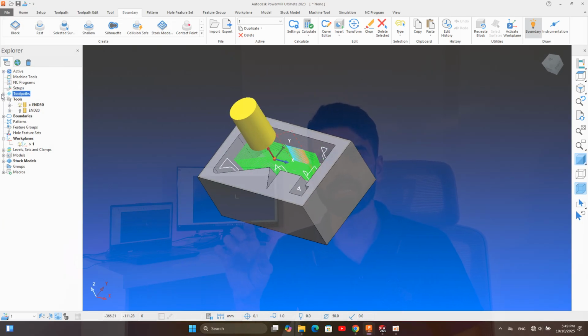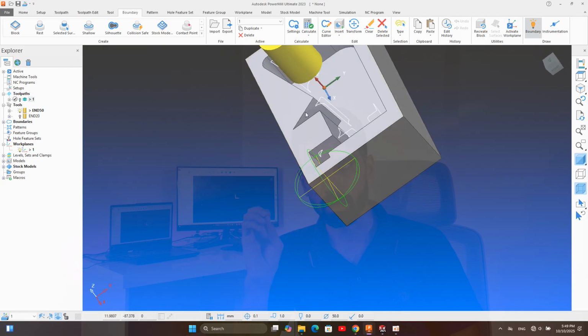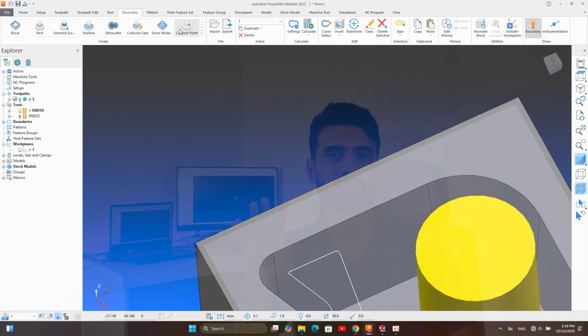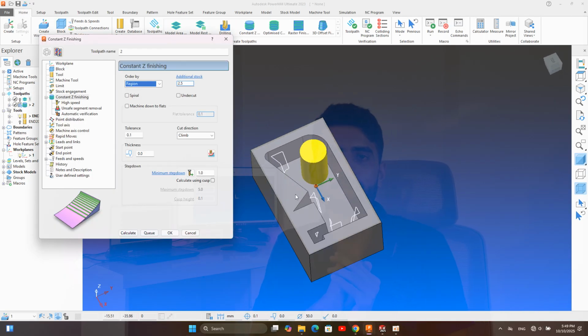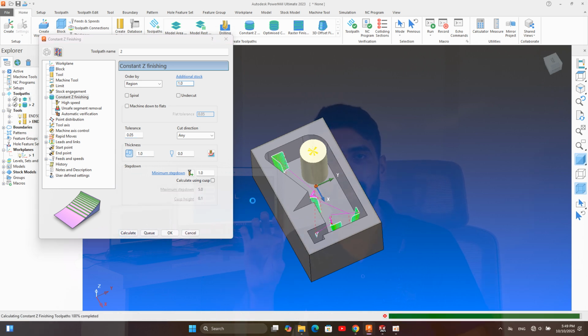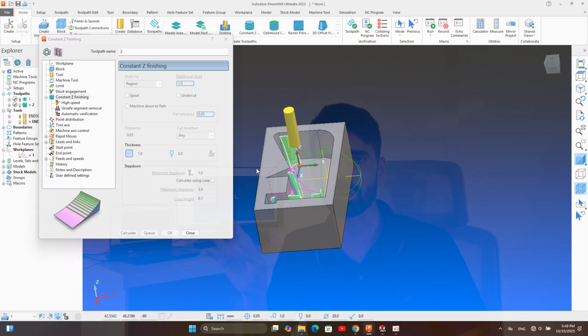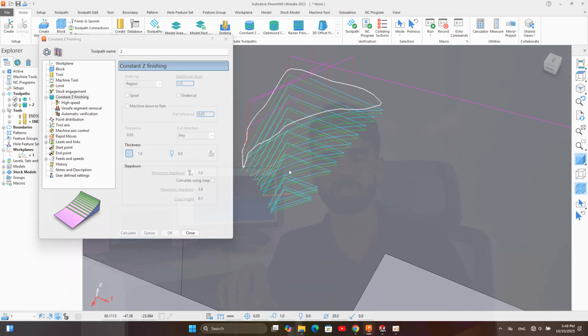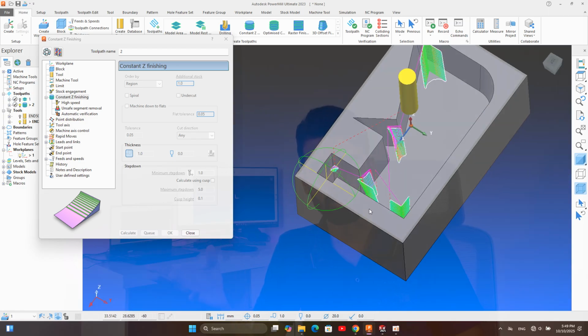And after that you have to set the tolerance of the boundary calculation. For any kind of boundary, I want you to use 0.01 millimeter every time as a tolerance. At least don't use bigger numbers. It gives you a better quality.